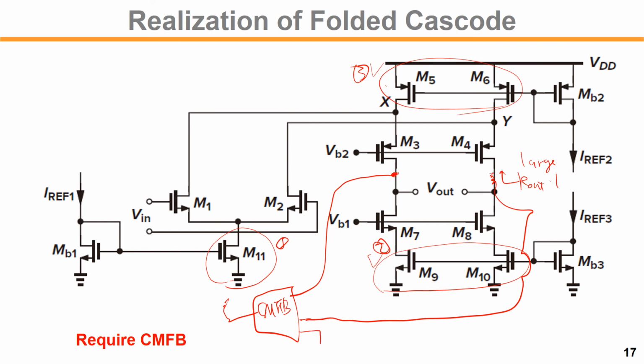So we have to make sure that desired output level with reference voltage is supplied. Typically it will be around the half VDD, right? So this output signal we have to control either current source 1 or 2 or 3, right? So this is more things that you have to study. What kind of common feedback circuits are there, and you have to understand what is the limitation of each case, right?